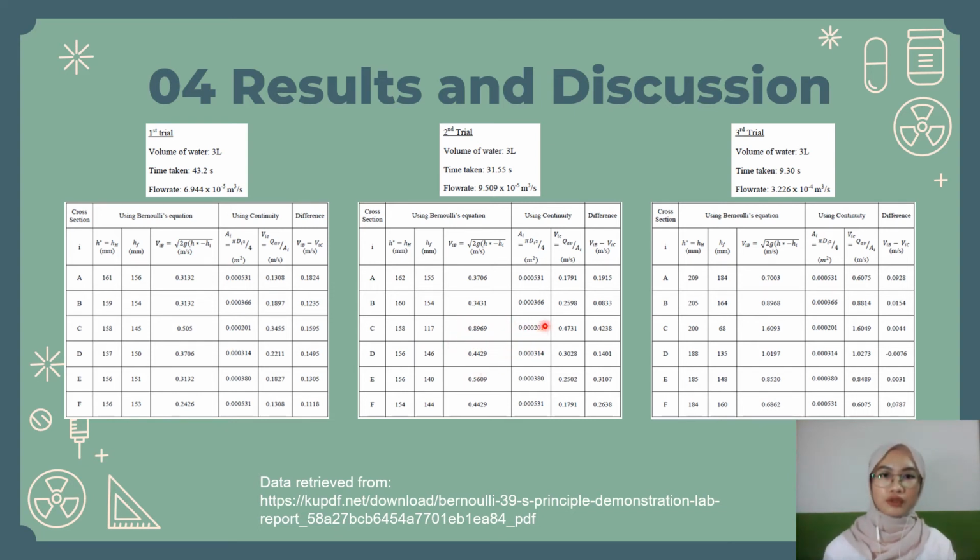Also, as fluid flows through the venturimeter, the head is higher at the narrower tube and vice versa. The narrower tube leads to high velocities and low pressure. Also, the highest volumetric flow rates gave the highest velocity.